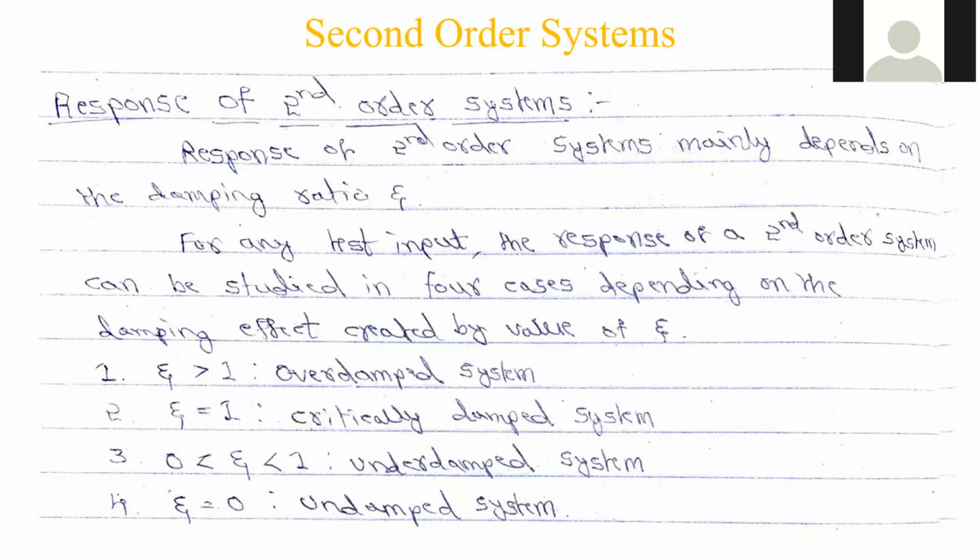Good morning all. So we will discuss today the unit step response of second order systems. As you know already, in the previous session we discussed the unit step response of a first order system. We got the transfer function, then substituted for R of S input, and modified that R of S for applying the inverse Laplace transform. Applying the inverse Laplace transform, you get a time response. That is called the final one. The same way we need to do it for second order system.